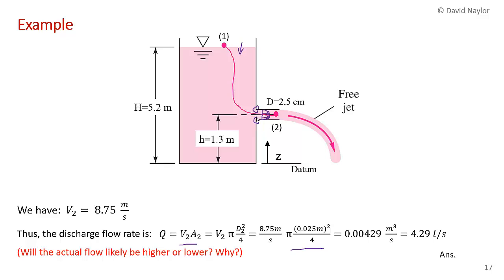These sharp edge inlets cause some turbulence, and that burns up some energy because of mixing. It dissipates some energy. And so Bernoulli's equation assumes there's no energy loss from 1 to 2, but in reality, there is some energy loss due to fluid friction. And so you'd probably get a value just slightly lower than this. But nevertheless, it's a very good engineering approximation for most flows.